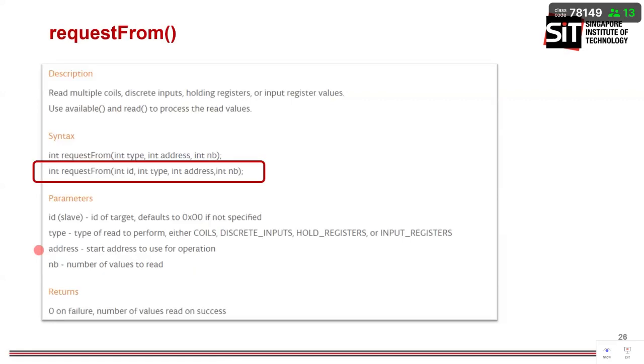Okay, so this is the part to establish the understanding on wiring RS485. So in this week's lab, you will have to wire up a sensor module with your MKR485. That part discusses the topic on RS485. Then when you write your code, in this particular case, you are using the Modbus protocol.